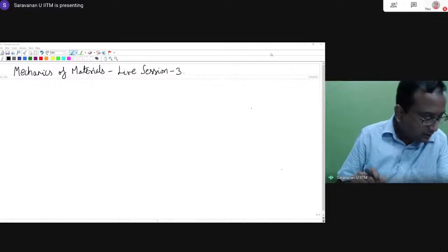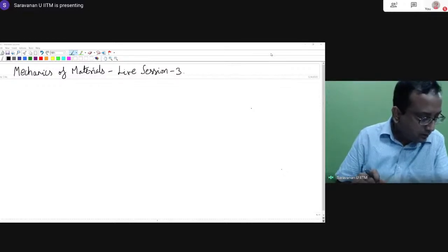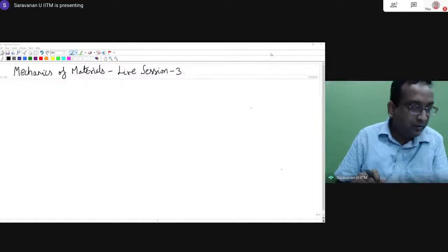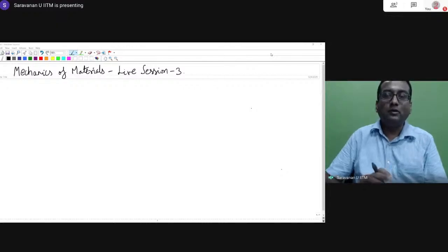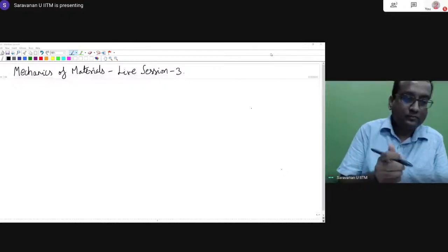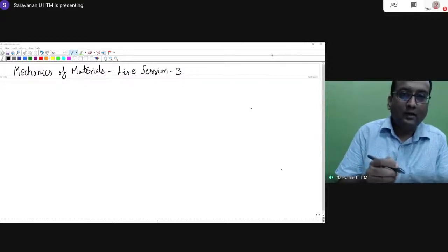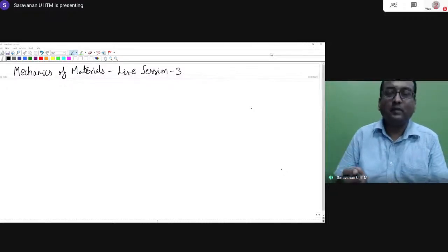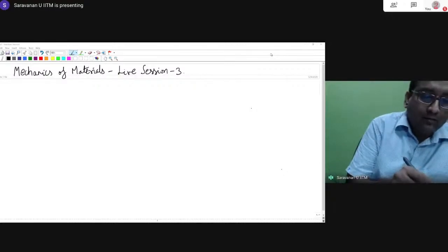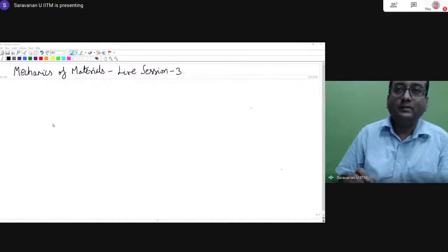And then there is a question on whether spherical coordinate systems are more suitable for what category of solid mechanics problems. Spherical coordinates are used to study inflation of a balloon and squeezing of a cone kind of problems. It's not a conventional engineering problem that you solve using spherical coordinates. So some special boundary problems like squeezing of a cone, which will occur in the case of a pre-stressed concrete beam at the edge zones.